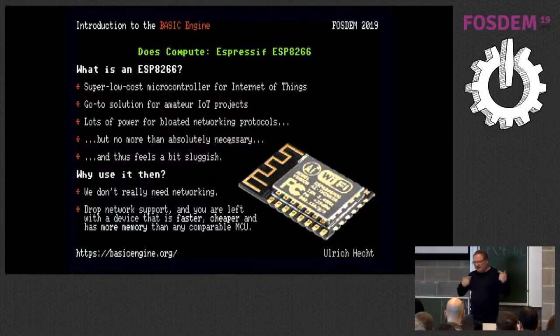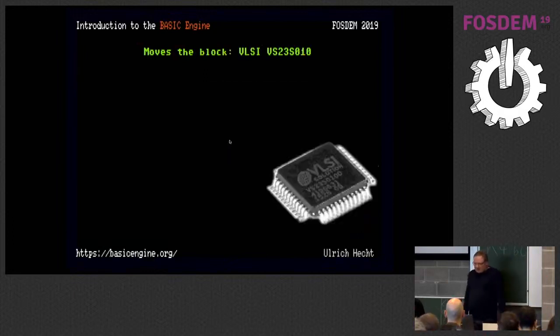You still don't have anything that displays stuff on a screen. We could do that in software again, but not so great. And also we need more memory, because the ESP8266 has like a grand total of 160 kilobytes, of which you can actually use 80 kilobytes for your program, of which a lot goes for various administrative purposes. What you effectively have free is about 61 kilobytes. You don't want to use that up for a frame buffer that uses 64 kilobytes, especially because you can't.